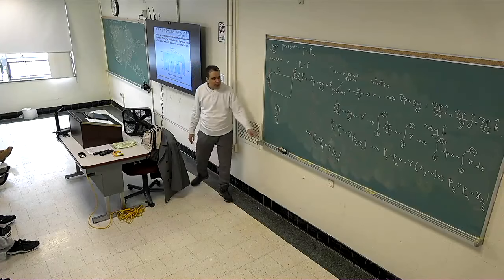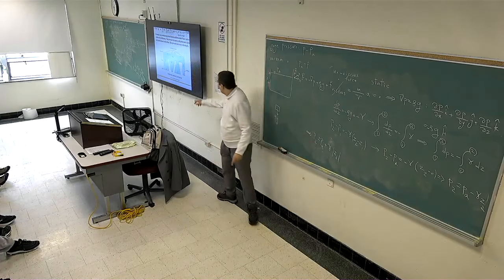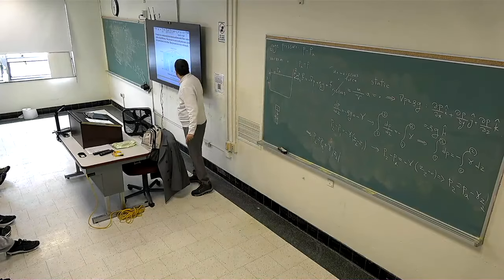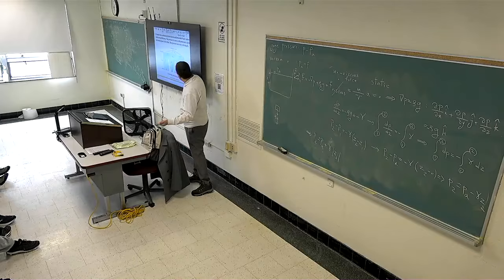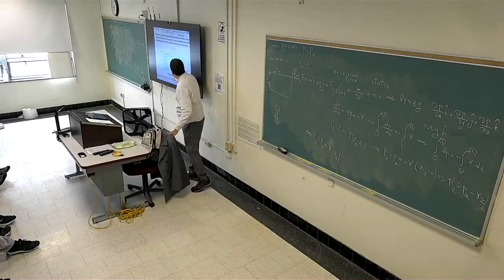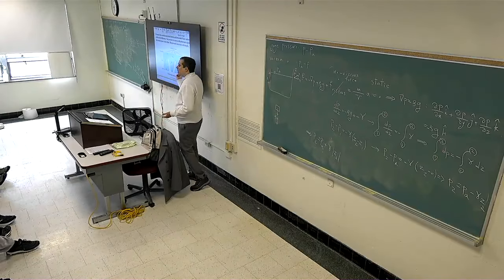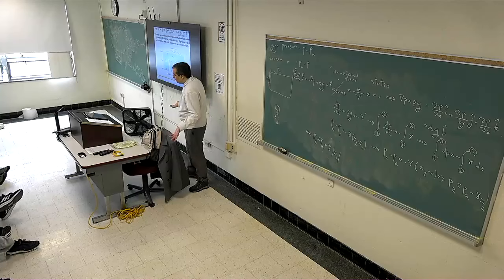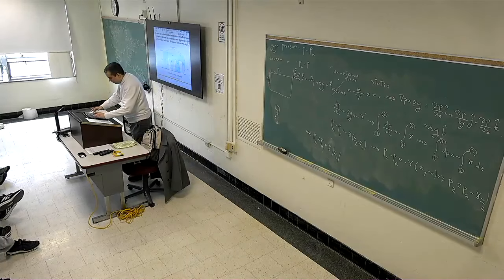Exactly, yeah. The pressure at D is the Z of the water section multiplied by gamma of water, plus the Z of this section multiplied by gamma of mercury. Gamma of mercury is higher, but the pressure at C is total Z multiplied by gamma of water. This has a higher gamma, so a higher pressure. That makes sense.